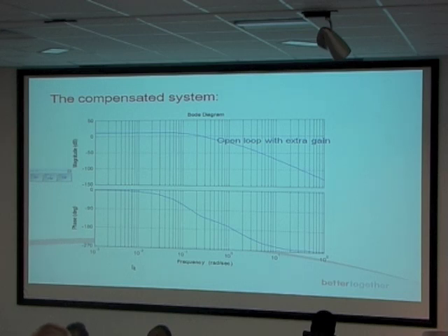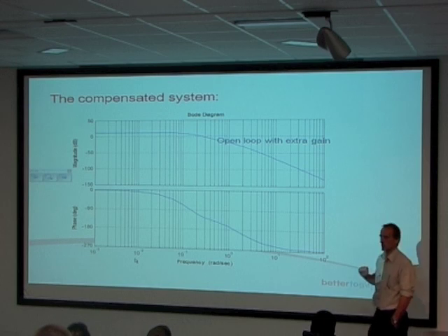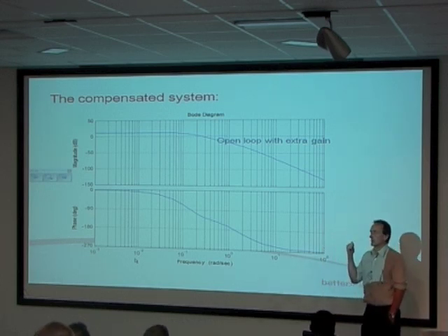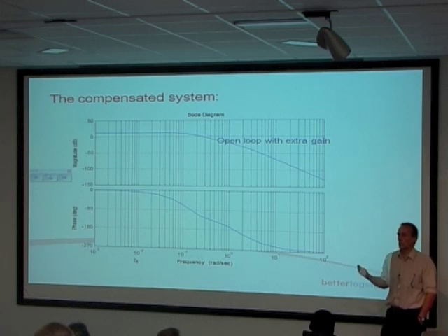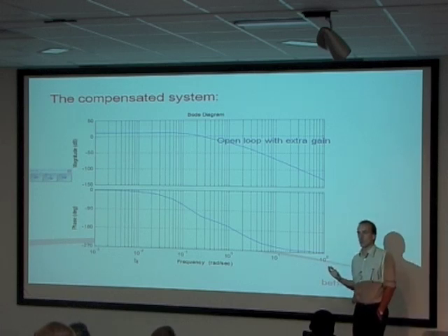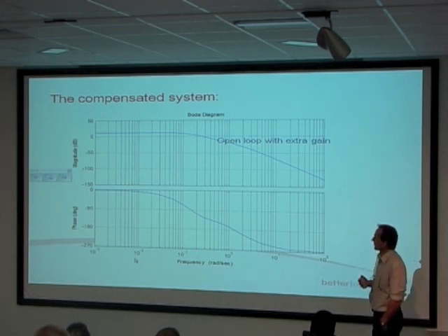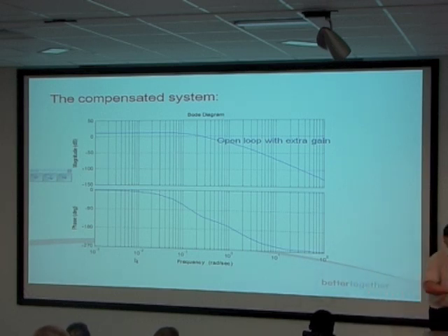Right, that's the system we're starting with. This is the correct slide for our system. Okay, forget the extra gain words. But this is our Bode plot for my submersible with the correct actuator on the elevators. Okay. Let's have a quick look at things like phase margins and gain margins.